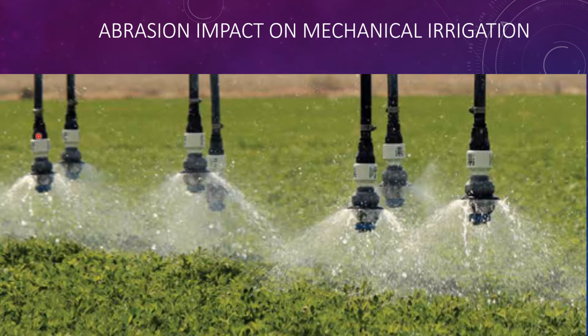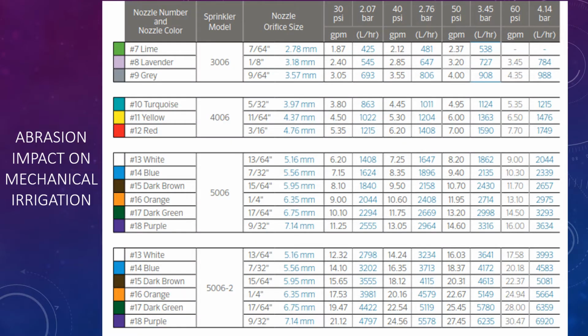They will abrade these and cause issues with fine particles getting into the pressure regulators, which can also cause problems with movement, and so you get a stuck regulator. And of course, as that water package starts to change in its ability to control the pressure and the flow, you get a dramatic impact on your water distribution uniformity. We'll take a closer look at that shortly.